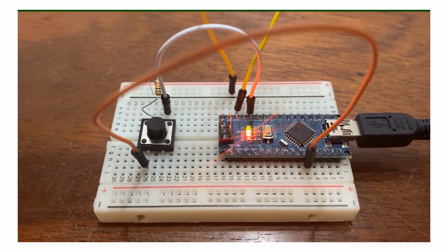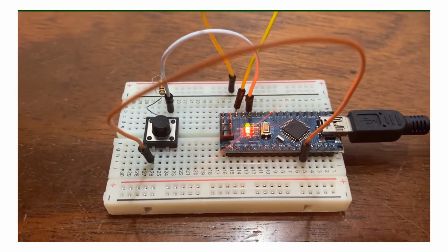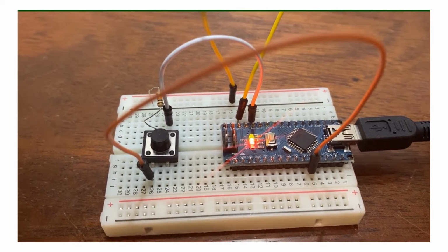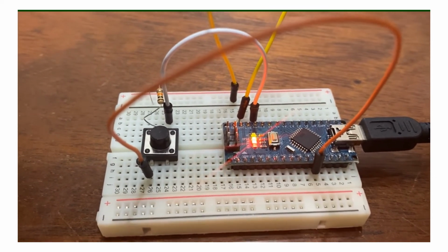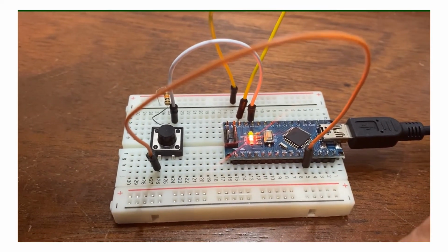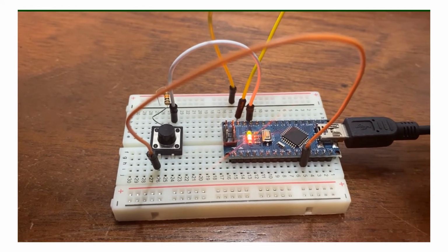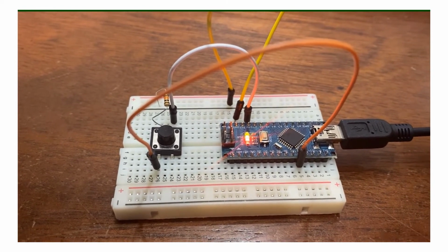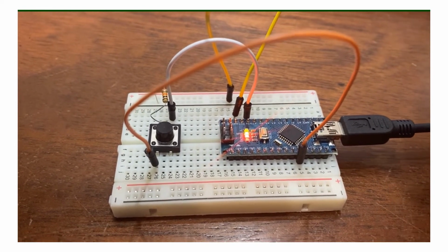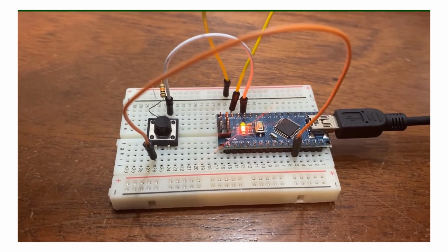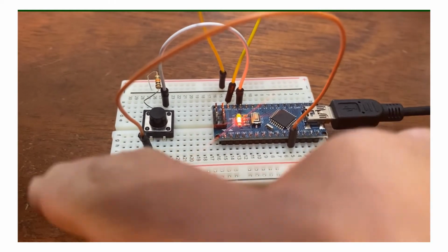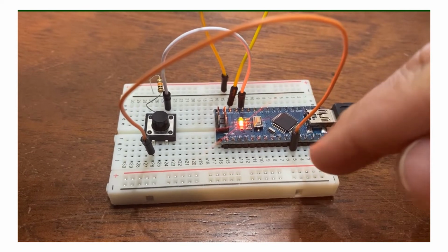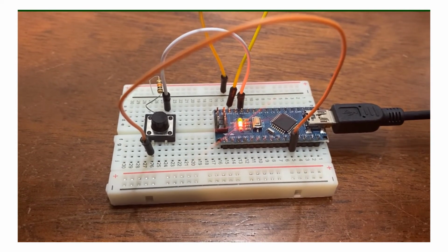Here we have the setup for the Arduino assignment Part 1A, which utilizes a button to open and close the circuit on command. Whenever the button is pressed down, the circuit is completed and the signal transferred to the Arduino program will be a 1. Whenever the button is released, the transferred signal will be a 0. Right here we have a button which is powered from pin 8, which is specified in the Arduino program.